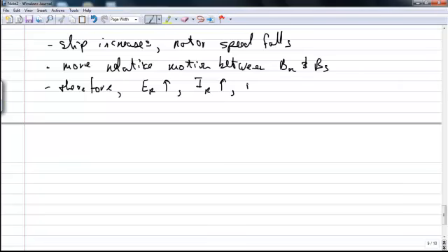And if IR goes up, BR goes up. So more voltage is induced onto the rotor. More voltage on the rotor means more current flowing in the rotor. More current flowing in the rotor means that the rotor magnetic field will get larger. The angle of IR and BR also will change.